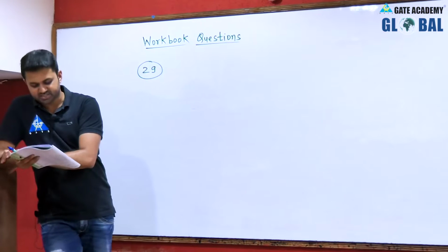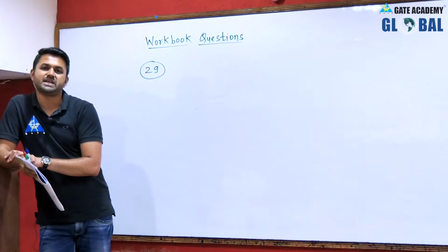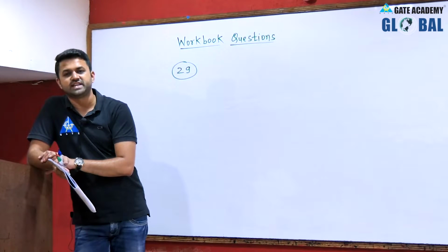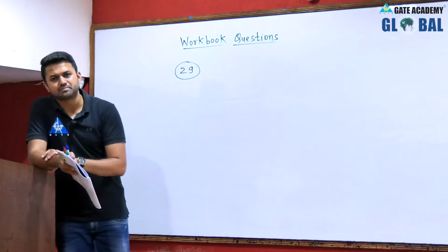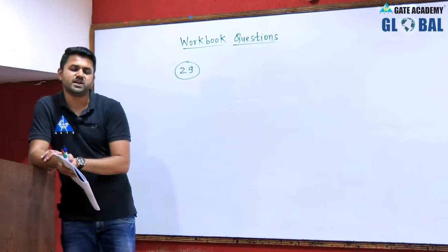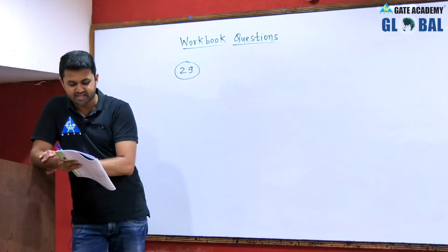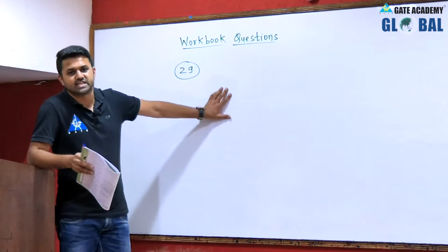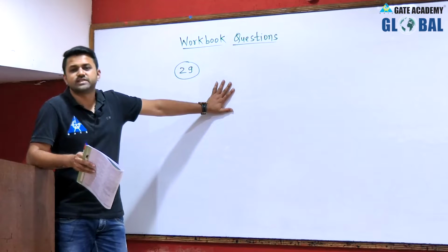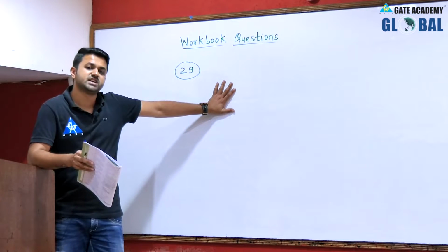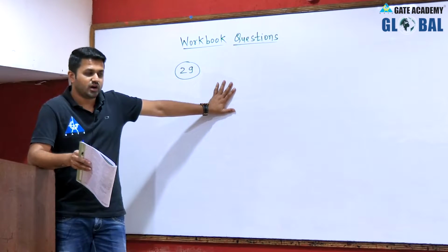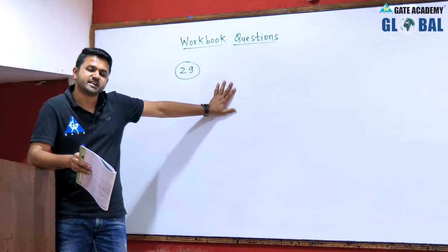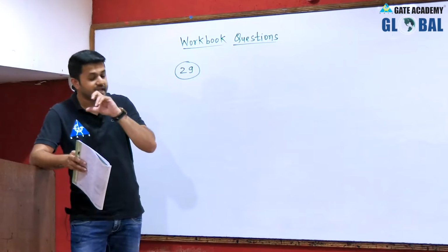And the bandwidth is 3 f_m. The band pass filter has a bandwidth of 3 f_m, but we took the bandwidth of the band pass filter as 2 f_m. So does it pass any extra term? It does not pass any extra term, because for the carrier frequency, we have seen that the condition in case of a square law modulator to avoid extra components was f_c very much greater than 3 f_m or f_c equal to 3 f_m.